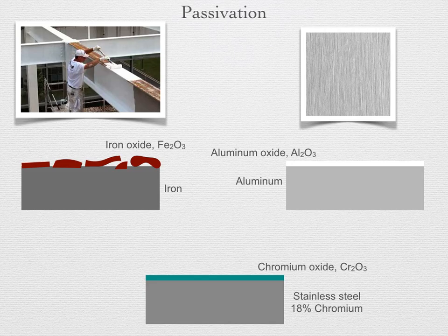Other alloy grades can impart different resistances. For instance, the presence of about 3% molybdenum produces type 316 stainless steel, which is also resistant to strong sulfuric acid solutions, which can degrade 304. A well-formed oxide coating, even if only a few nanometers thick, can still protect a metal from additional corrosion by keeping the cathodic reagents away from any metal.